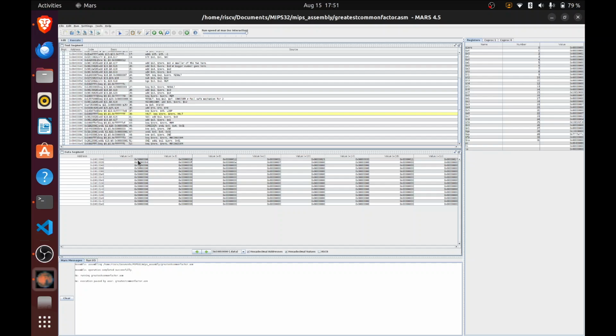You'll be able to see the data segment here, where whatever was defined in the data array will still be seen, starting from 618, and it's given in hex by the way. Let me go to the result, here you can see the result at 200. 6 is here, 7 is here, it's in hex. So 11 is basically 17 in decimal, 1 is here, 5 is here, and 0 is here. So you can see that it worked well.